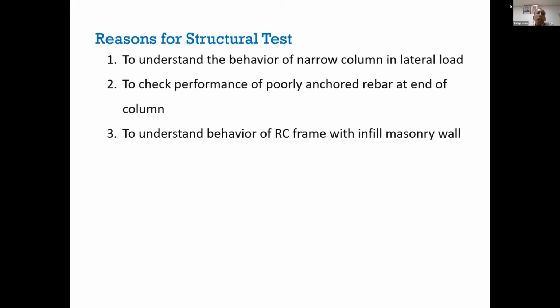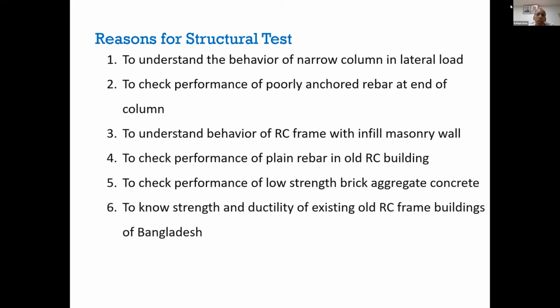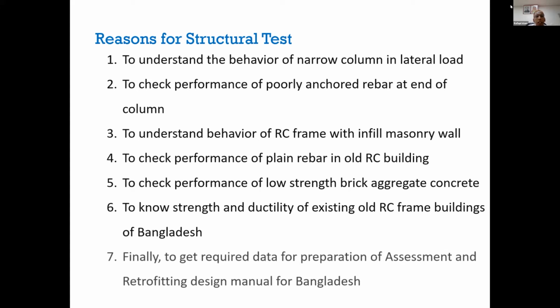that is not available in Japan. Further objectives were to check the performance of plain rebar in old RC buildings, to check the performance of low strength big aggregate concrete, that is low strength concrete in highly axially loaded columns, to know the strength and ductility of existing old RC frame buildings of Bangladesh, and finally to get the required data for preparation of the assessment and retrofitting design manual for Bangladesh.